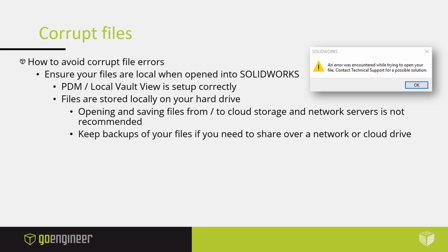The biggest piece of advice I can offer, obviously PDM. When possible, use PDM. PDM is free if you have professional or premium SOLIDWORKS. Make sure the files are stored locally on your hard drive when you're opening or saving them, to and from the program.